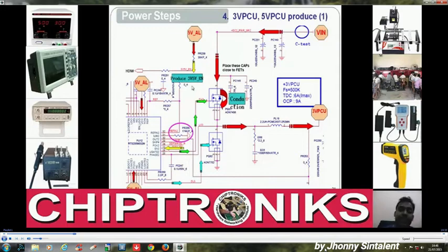They will generate this signal when they get the enable signal, and the enable signal in RT8206M comes from LDO, and LDO will get generated when V in through resistance divider goes to the enable LDO pin.